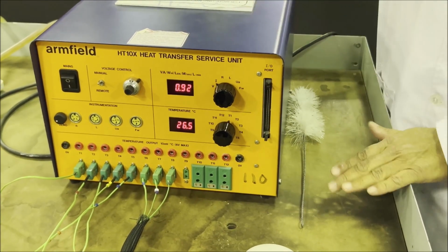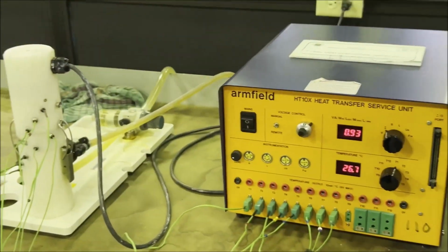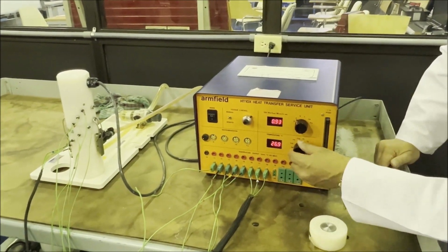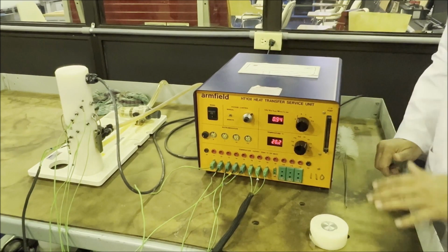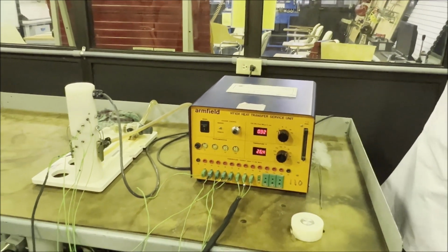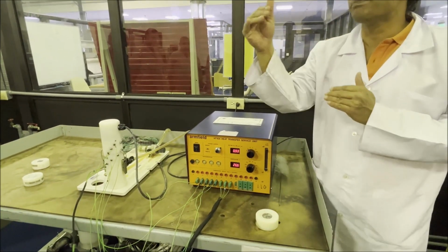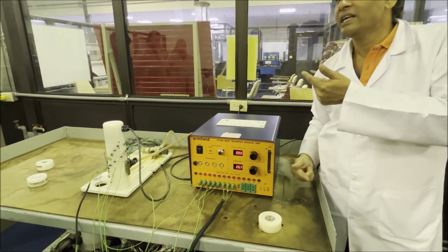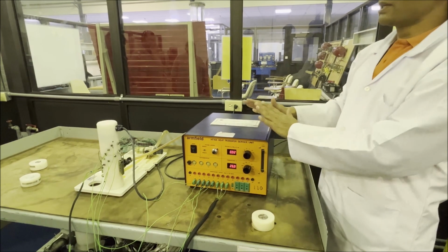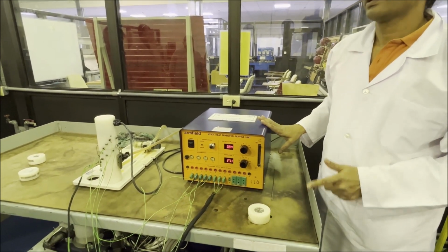So this will increase and then heat is flowing. This is T1, T2, heat is flowing downward. So you can see T1 increase. Put it on T2. T2 will also increase, and then become steady. There is no change in temperature with respect to time, which is called steady state. So when the system reaches steady state, meaning there is no fluctuation in number, record the readings.